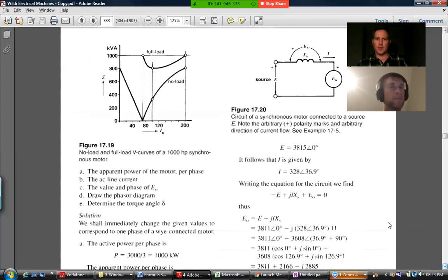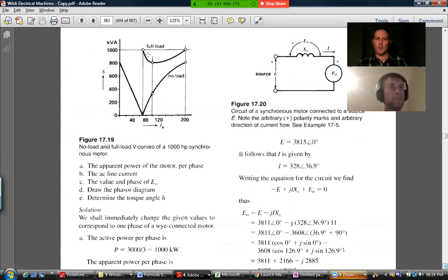V-curves, purely out of interest. Main thing that we're looking at here is that as you adjust the excitation, you inevitably end up affecting a little bit of both the reactive power and the real power. So there'll be a specific spot where you've got your rated, this is IX, that's the exciting current. So as you overexcite it,